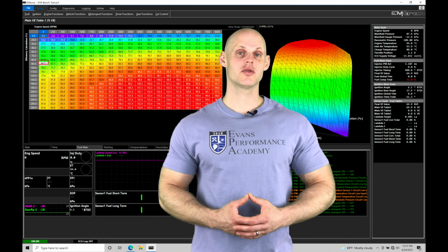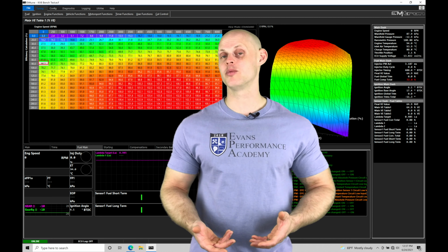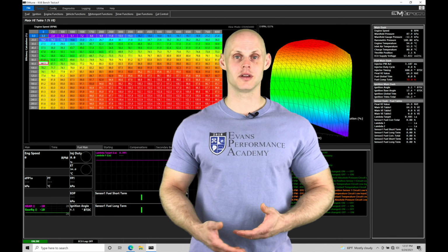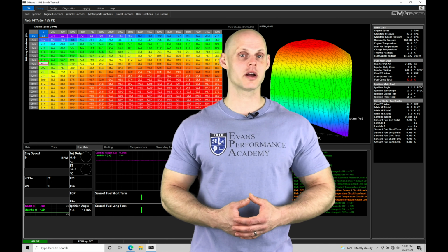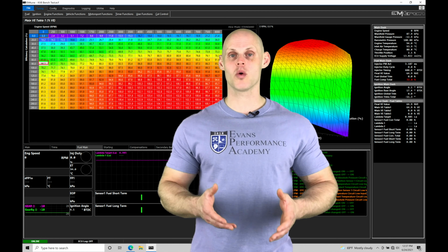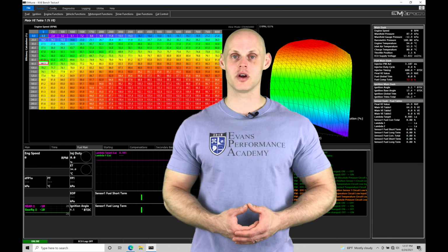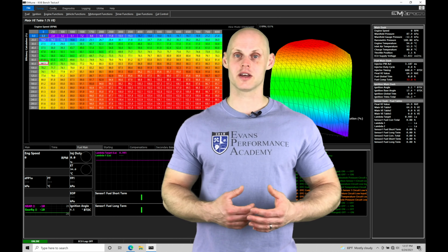In this training tutorial, we're going to be taking a look at setting up our advanced analog inputs. Our advanced analog inputs are things like fuel pressure, oil temperature, switched type inputs, or even custom inputs that we're able to define, something like coolant pressure, for example. We're going to take a look at a couple of different examples of how to set up and work with our advanced analog inputs in our training tutorial. Let's jump in so we can check this out.